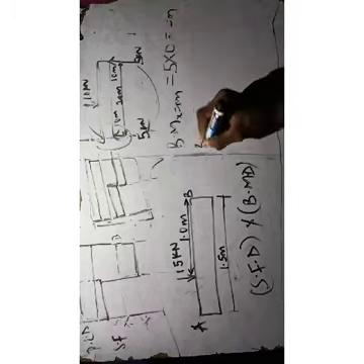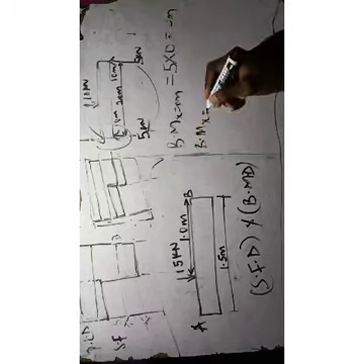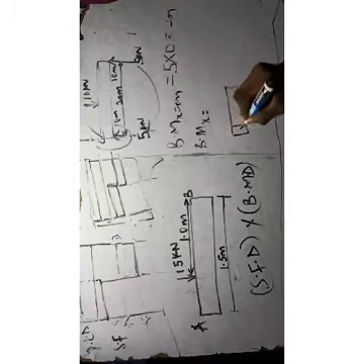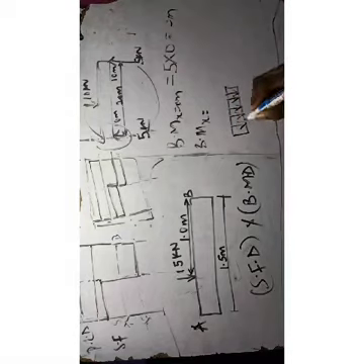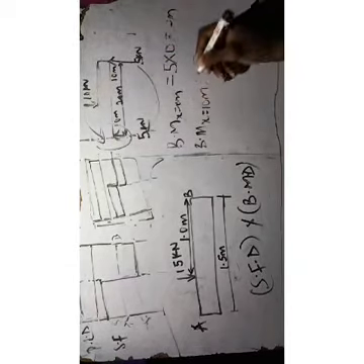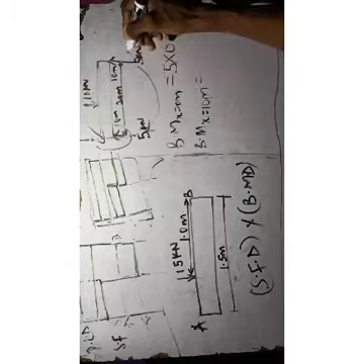And next one, the bending moment when x equals to, here you try, make sure you section this very well. If it were to be a UDL, uniformly distributed load, like this, like this, you need to pick your x and section it very well. Like you take it for equal distances, 1, 2, 3. But in this case, we can jump to 10. So when x equals 10 meter, if it is to be UDL or VDL or combined load, you don't jump.